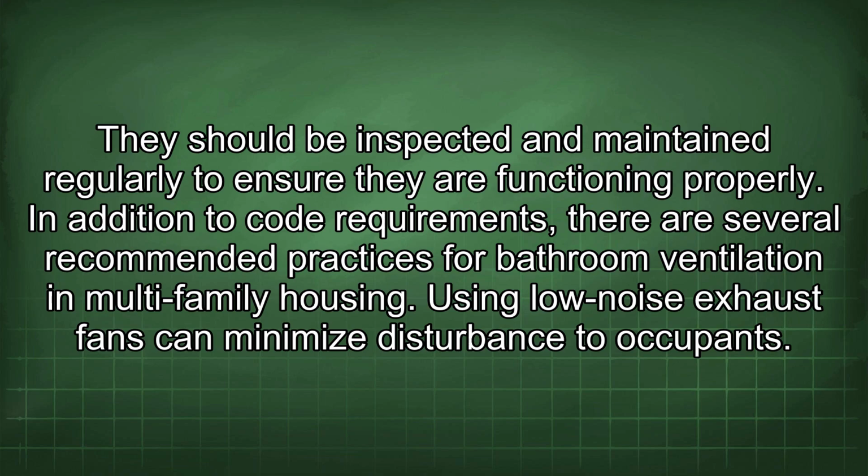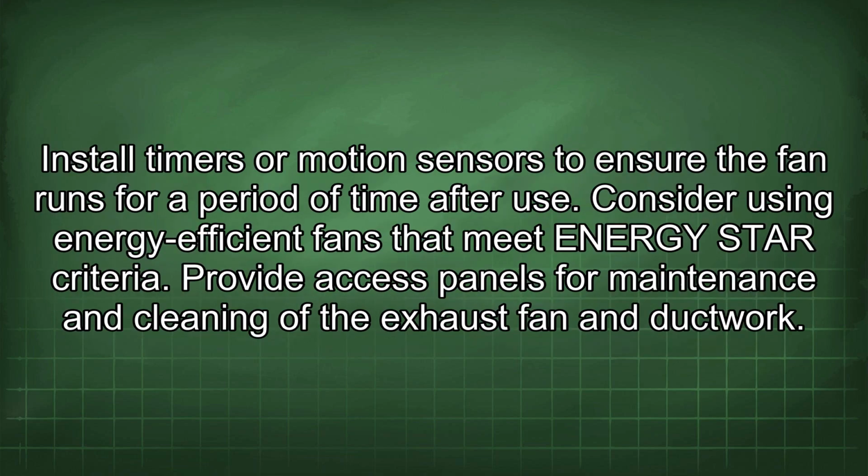In addition to code requirements, there are several recommended practices for bathroom ventilation in multi-family housing. Using low-noise exhaust fans can minimize disturbance to occupants. Install timers or motion sensors to ensure the fan runs for a period of time after use. Consider using energy-efficient fans that meet Energy Star criteria. Provide access panels for maintenance and cleaning of the exhaust fan and ductwork.